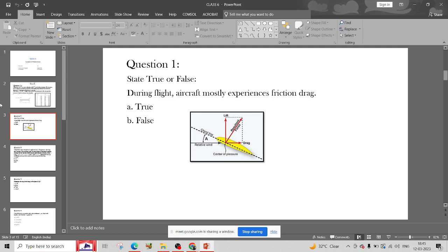Okay. But at the same time, keep in mind that streamlining also increases the friction drag. Thus, the more you streamline an object, the more elongated its rear surface will be, and the more you reduce the size of the wake and the resulting pressure drag. But elongating an object increases its surface area and increases the effect of friction. That is another form of drag.